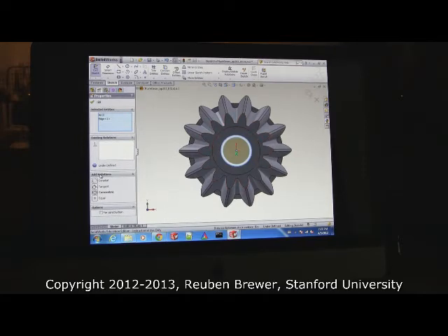We did it for the other circle. We're doing two circles. Hit co-radial. See this button right here? I don't get that button. If you don't get that button, both circles are not selected. So you have to select that. It's a hole, right? Okay, now you got co-radial.